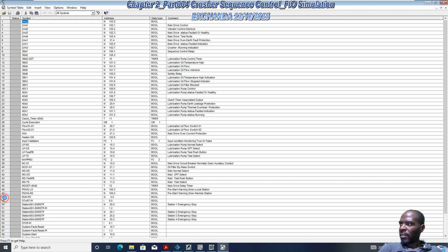It's right about here. We just change this to this, and then we just say PI. We save this. Pre-start warning siren assigned to physical output address Q4.0. So save that and close this.